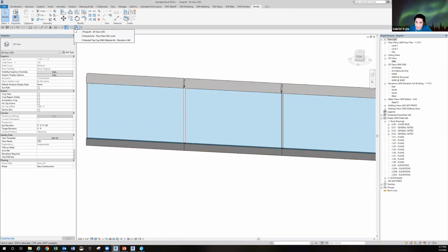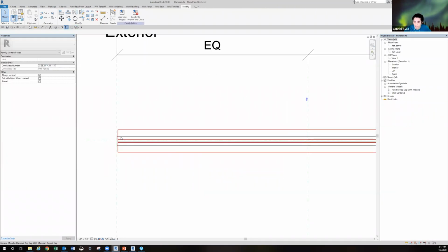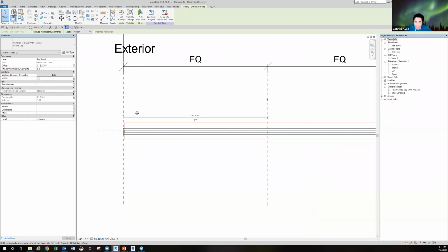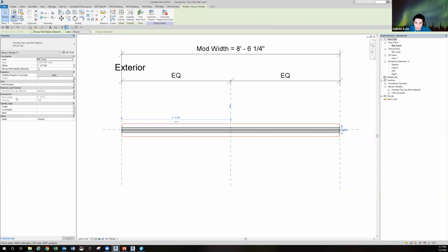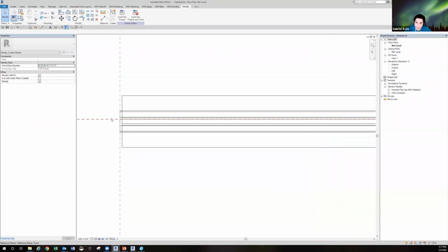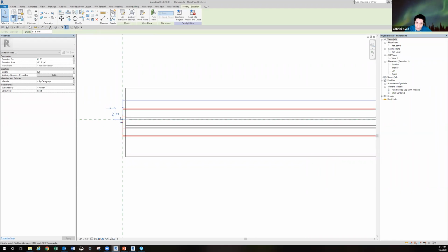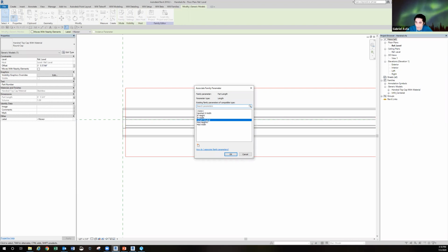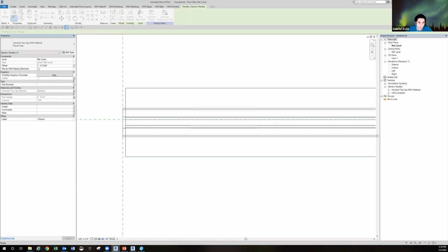So in that case, if you go to your handrail, you can do the same thing for the cap. So the cap right now, the way it's made, is being driven based on a formula. So it's saying the part length. I was able to drag this to the edge because this is kind of an extrusion created in this family, but the cap is actually an extrusion created outside the family and brought in and controlled based on the part length, as you can see here. So it's saying it's 8'5 3/4", and that is driven by the length of the handrail, and that is actually a formula.